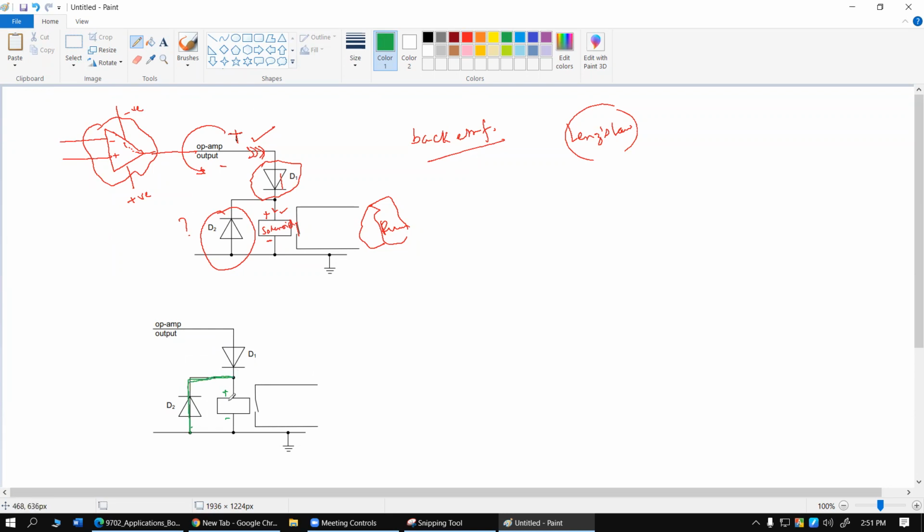The purpose of this single wire would be that whenever this solenoid is trying to draw more current, whether this is positive or negative, no big deal, you can draw the extra current through this path, and this current will flow through this loop for a small duration, and the whole thing will be just fine. So the current will go through a very small circuit, not affecting our op amp that is connected over here, so that we can save the op amp. So a single piece of wire for bypass should do the trick.